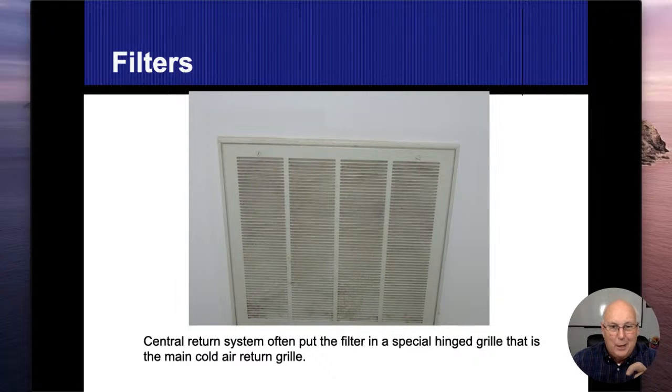So I'm going to take one of those dial thermometers or turkey thermometers or whatever other device I have. I'm going to measure either the air where the filter is, which is pretty much the room air, and you could see that on your thermostat. And then I'm going to go above the plenum and measure that temperature there as well. And if I'm too high, I like to remove the filter and see if that lowers that temperature back down to normal. Because if that filter is restricting the airflow and now my circulation air is slowed down coming across that, it's going to absorb a lot more heat. And that actually shortens the lifespan of these furnaces.